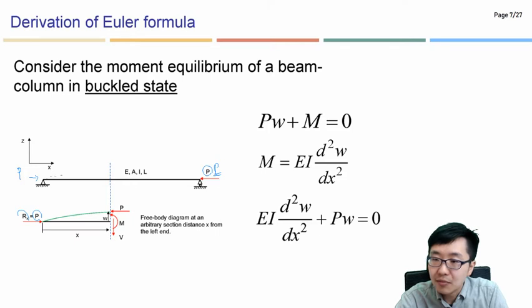And once we apply the actual compression, of course, this beam will be deflected like this or that, but we will just assume it this way. And then we are going to have this much deflection W. So just assume that this is X and cut the section, bring it, this green color is our column, and the applied force is P. Because we cut the section, we will experience the shear as well as moment.